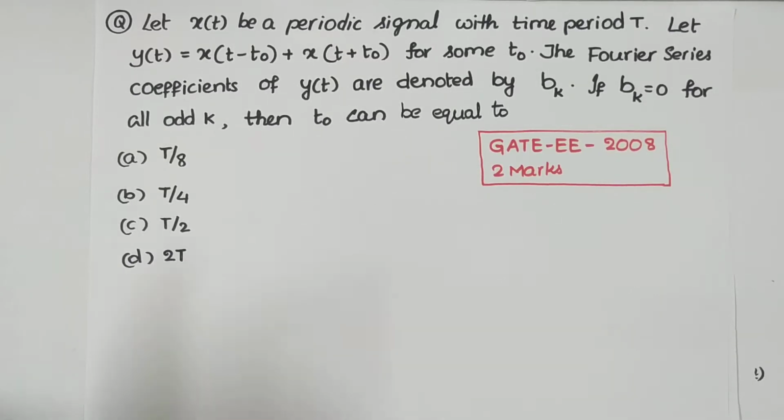Fourier series made our life very simple, right? For example, you have a non-sinusoidal periodic function, say in the time domain. And if you give this quantity as input to a linear time invariant system, the steady state response of that system we can find out very easily using Fourier series techniques. Yeah, because any non-sinusoidal periodic function we can express in the form of an infinite number of sines and cosines, if at all there exists DC as well.